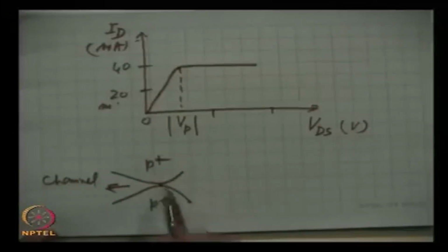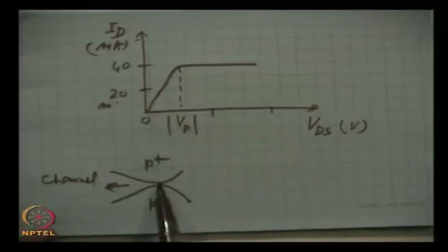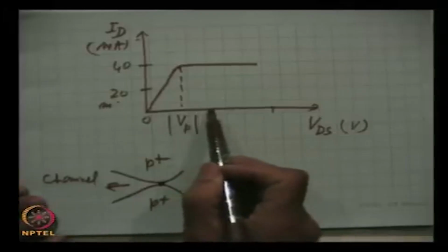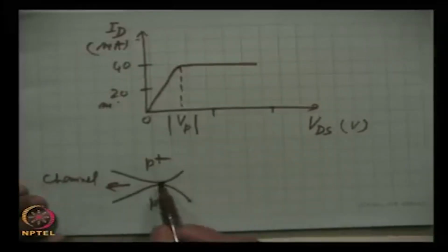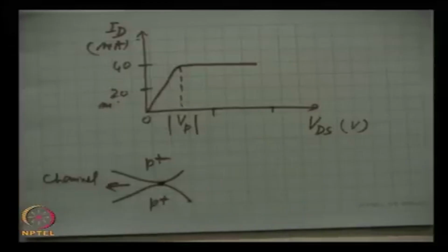and at the pinch off, only at a very small region at one point, the two depletion regions are contacting. As we increase this voltage, this contact region increases.